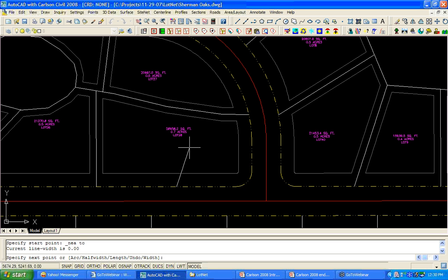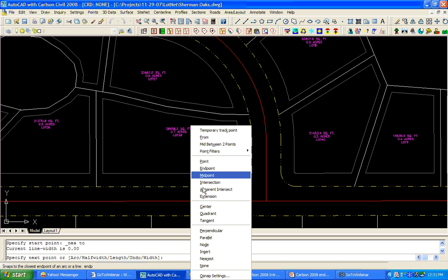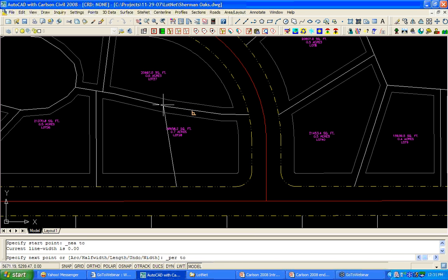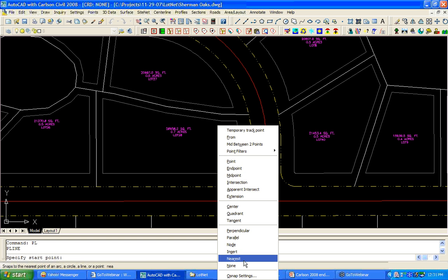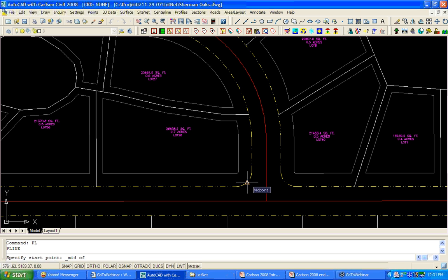Hey, Jim, you there? Or Lad, are you there? Yeah, I'm still here. Do you guys know where that radial... I believe there's a new command put into the software. Well, if you draw in a polyline, you could actually draw it from, if you choose a perpendicular option and choose basically like your curved part of your line, you actually start from the arc using a perpendicular, and then what you need to do is draw the line through the back edge that you were looking for, and then trim it off. What I could do is do a midpoint, something like that.